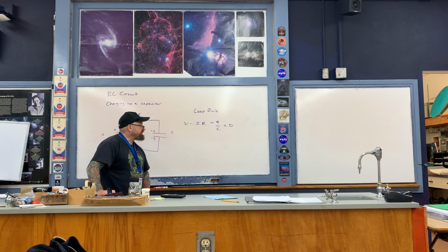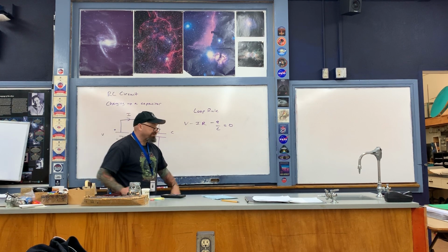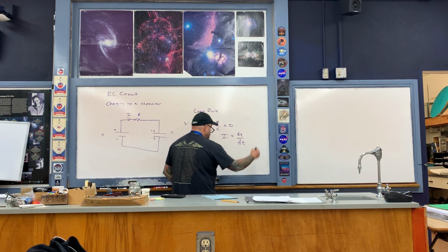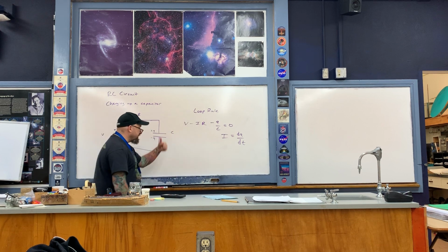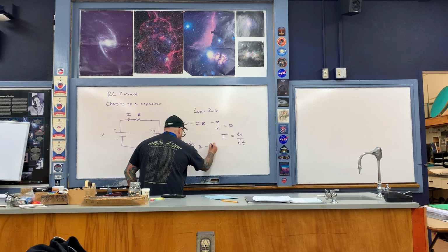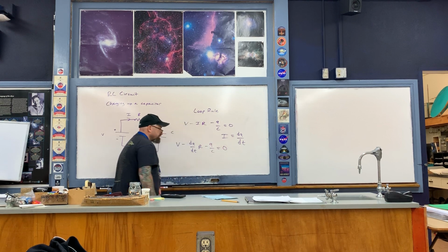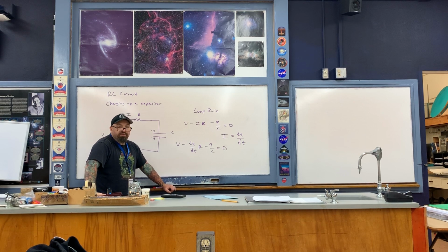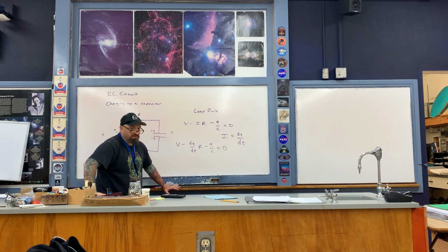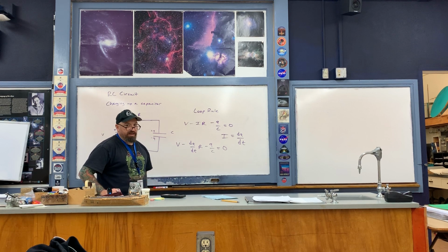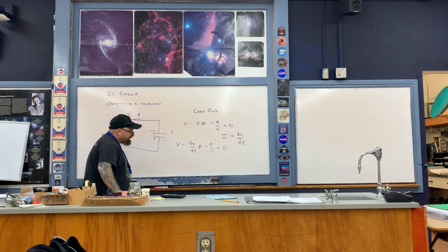This right here is not an algebraic equation. It's a differential equation because remember that the current I can be written in the following way: I is equal to the change in charge with respect to time, dQ/dt. So let's go ahead and write the differential equation like this. Now in order to solve this differential equation, we're going to separate variables just like we did with the air resistance differential equation. This is actually identical to the air resistance differential equation, just with different symbols and of course in a different context.